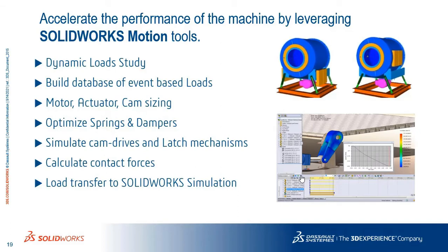So if I talk about a few benefits, you can create your dynamic load studies, you can build a database of event based loads, right? With the help of various loads, you can do your motion studies, then motor sizing, meaning what wattage of motor is required to trigger the mechanism. All these things can be found out. You can optimize your springs, dampers, right? If there are any cam drives or latch mechanisms, right?